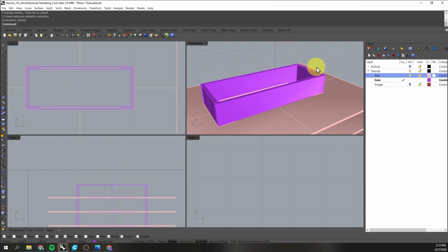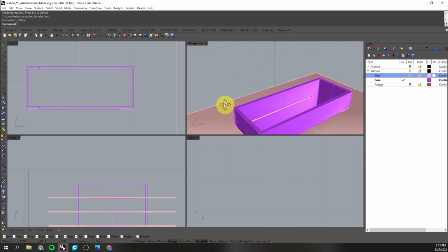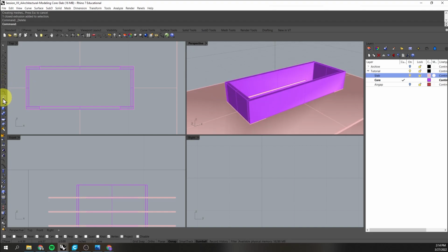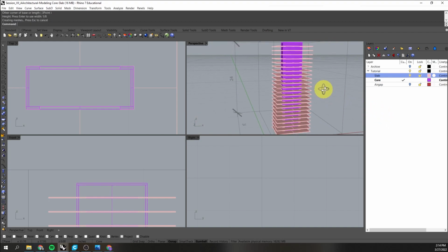Now that cleans up that top surface, and we can probably put a nice little cap, right? So like so, we can just make a box from there to there. That is the thickness of the material, 1/8. There it is.